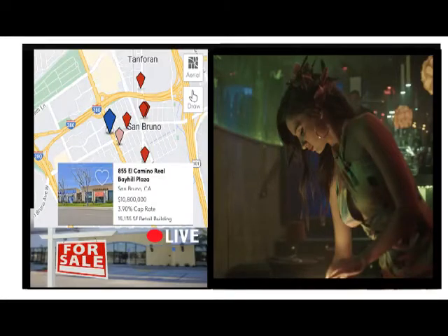The post and beam frame, used less frequently than the platform frame, allows great design flexibility. Ceiling boards are supported on beams that rest on posts placed within the house. Because the wall frame studs do not have to bear the full weight of the ceiling and roof, they can be spaced farther apart, allowing for greater room area. As California earthquakes have demonstrated many times, ground movement can create tremendous forces that buildings withstand only if they are properly anchored and braced.